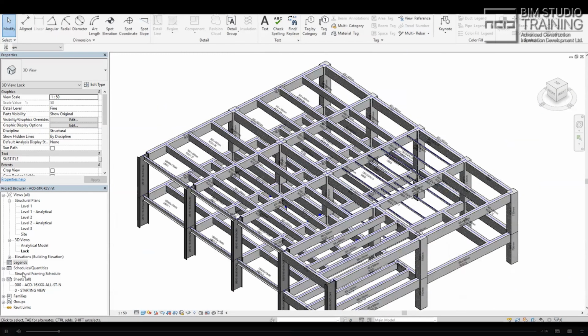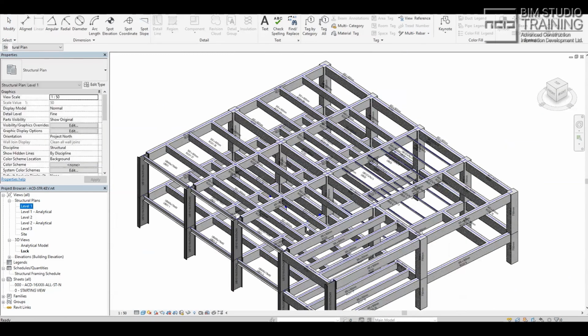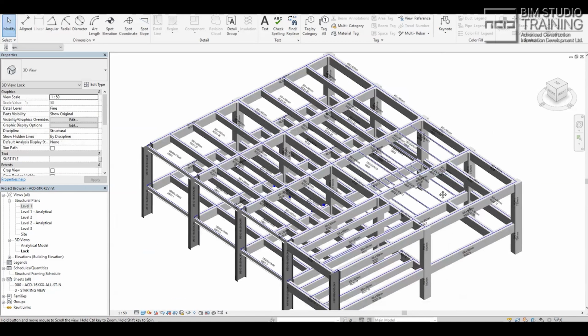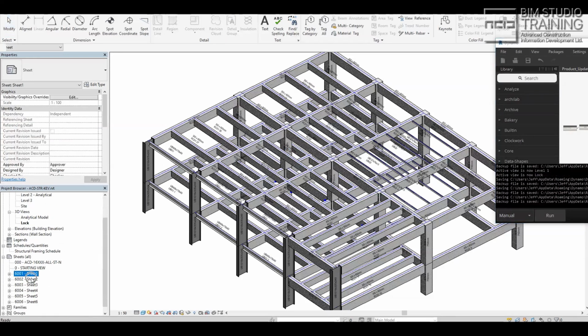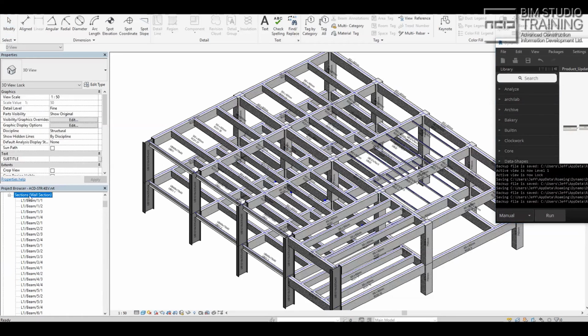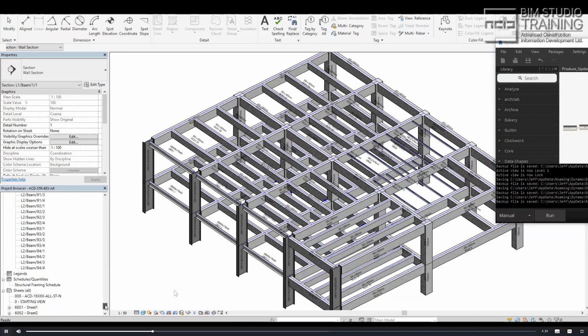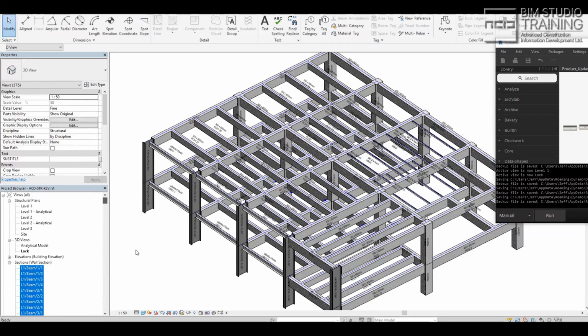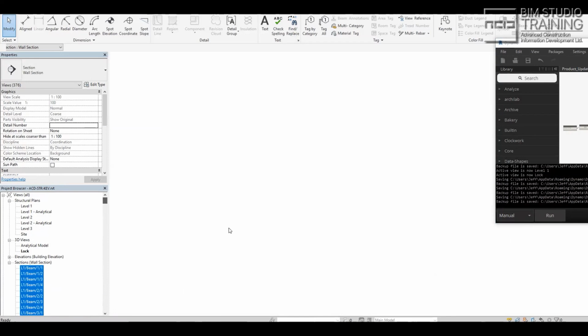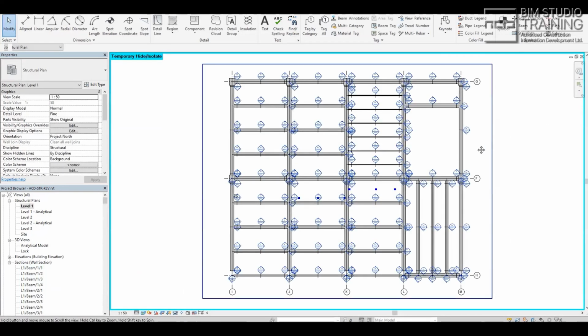So we do the same typical thing. We write scripts and run the script. We use the thinking of how the engineer thinks, and produce drawings. So I'll show you the result. Tell Revit, for every single beam, you need to cut a long section and then three short sections and put them on a sheet. Okay, this is the result.